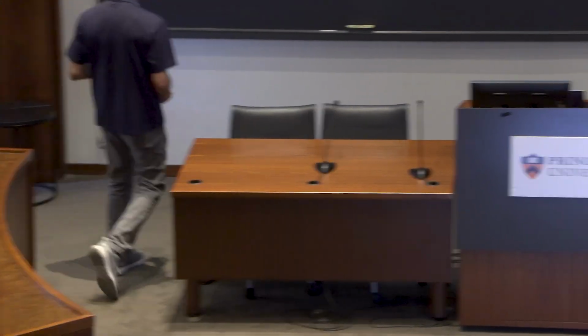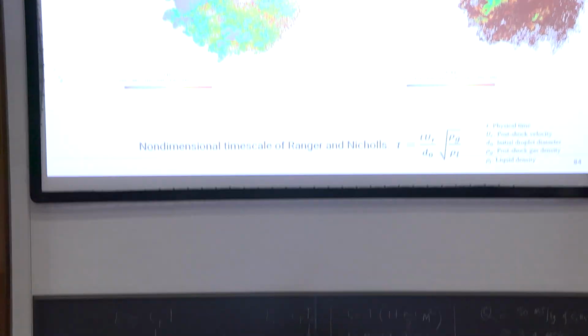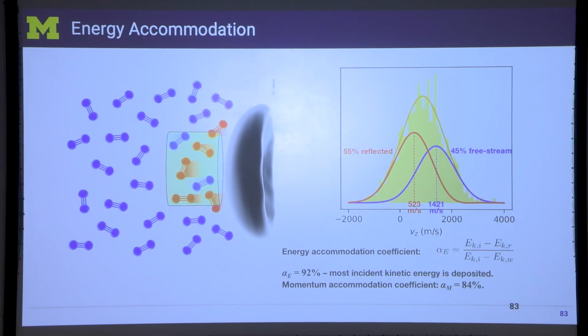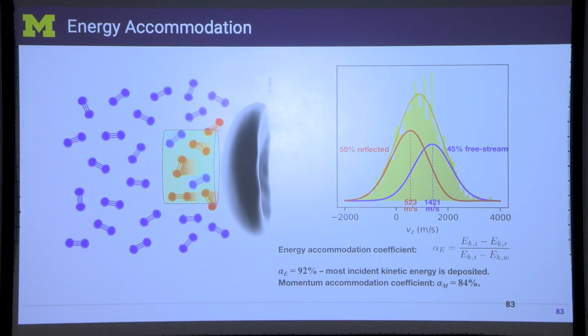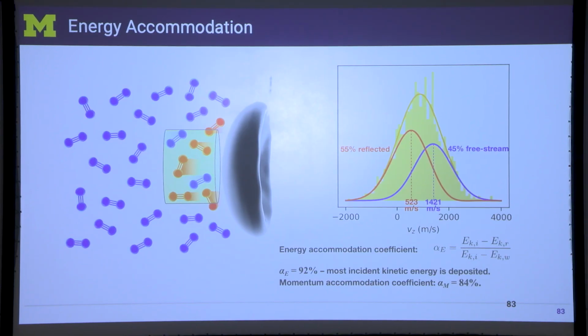Now the part that Nick and Wang figured out, which I think is important, and I'll go back to this, is this idea that when you have these molecules in the gas phase which are coming at very high velocities, they impact that pancake droplet, which is the one in the middle. If they impact it, the energy transfer can be significantly faster. So instead of having a conduction-based energy transfer that depends on the static temperature of the droplet and the static temperature of the gas, you might have an energy transfer that's based on the stagnation temperature of the flow and the static temperature of the droplets. And at high-speed flows, the stagnation temperature is very high, right? So the rate of energy transfer can significantly increase. So if you do this, you will have a very high evaporation rate. So it's possible that something like this happens.